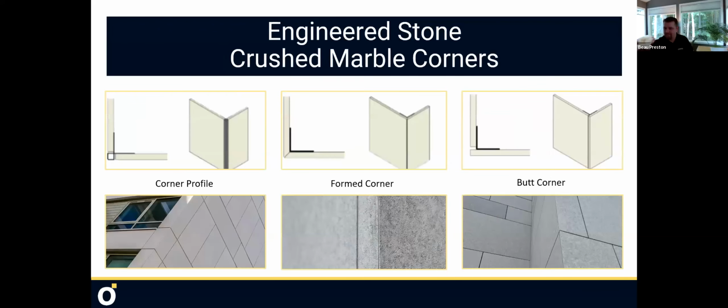Okay. Cool. And then now a big issue that people have with open joint rain screens, particularly when they have cores and different colors and such, is what do we do on the corners? The owner doesn't like the corner. The owner doesn't want to see in there. And when you do come around a corner, you have to pick which one's sitting proud most of the time